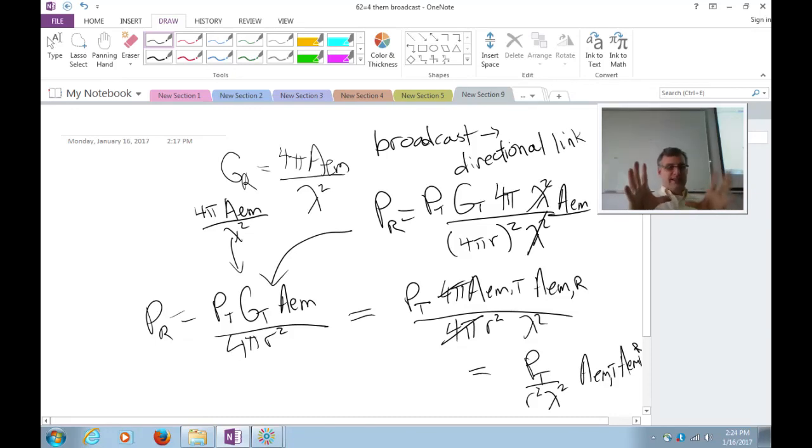And so our antennas at the base station, they get gain in this direction. They kind of squash the beam down. They elongate physically in this direction to squash the beam down in this direction. And then they also focus into sectors. So it kind of resembles this case where you've got a directional antenna that you can point in a certain direction. And so it's a little bit closer to scenario number 2 than scenario number 1. Well, that means that the system becomes somewhat frequency independent.